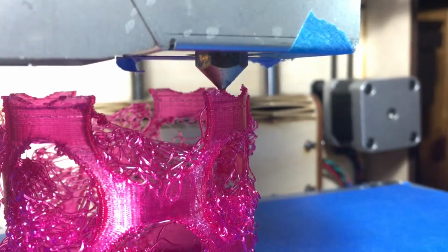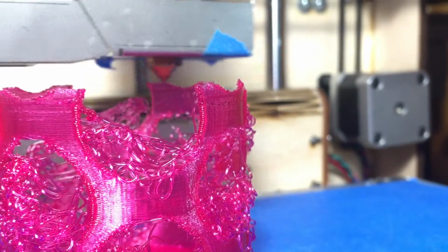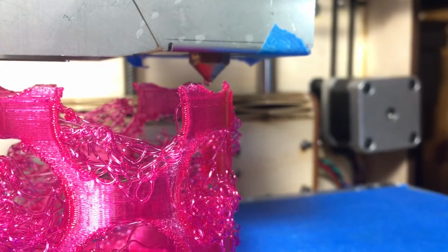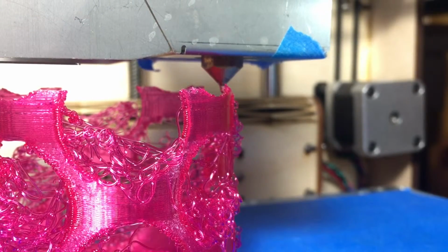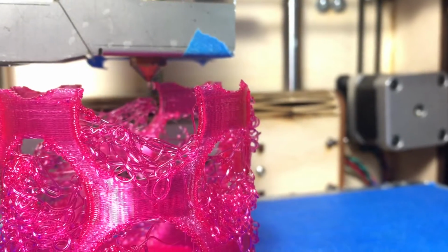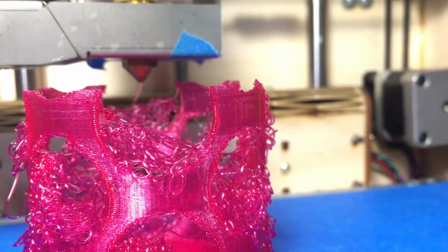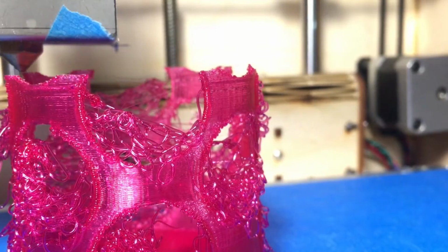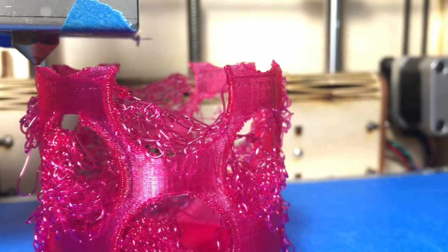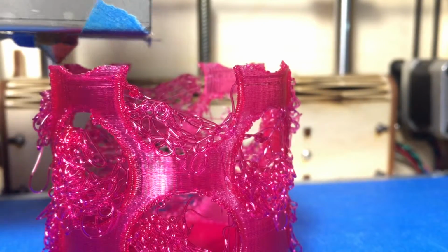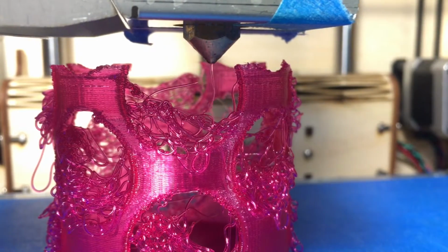Here's the printer. It's printing the wall part of the vase. It's going along normally. This is typically what you'd see, and now it'll change its behavior. When it prints the part that goes on the inside of these holes, it's going much slower, and it's extruding a lot more plastic. It has to go slower because if you're going to extrude a lot of plastic, you can only get it through the nozzle so quickly. It can move faster when it's printing the walls because it's depositing a lot less plastic. So this is basically something you do in the slicer.